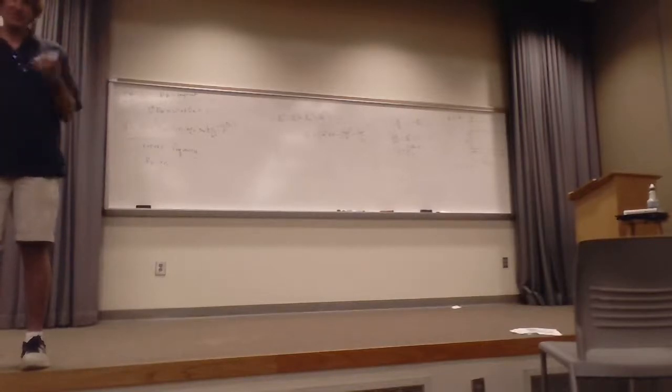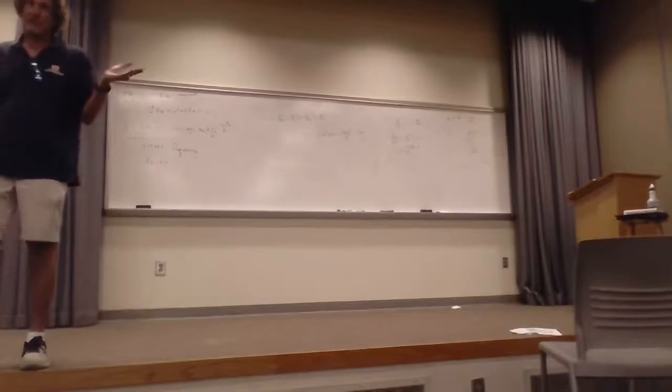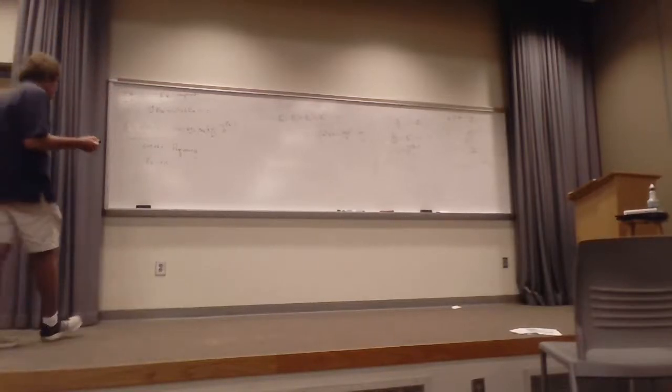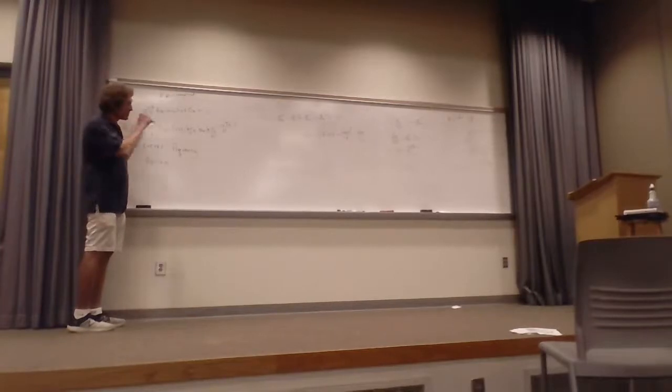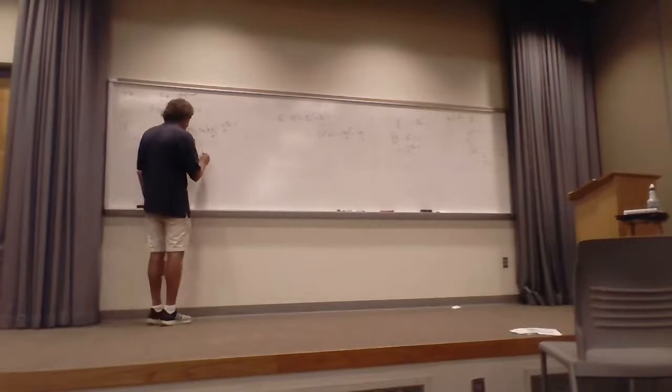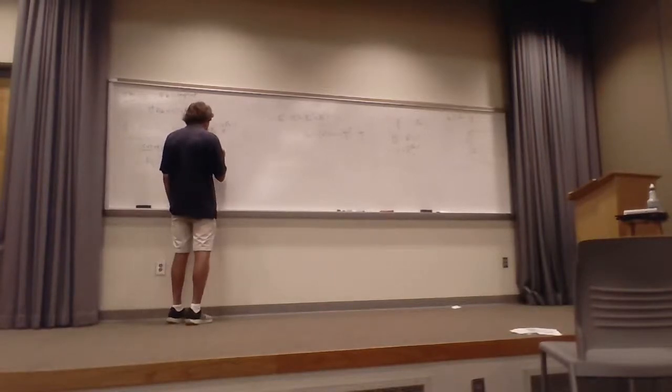It's not moving this way, all right? That's what it means. There's no z movement. It's only bouncing between, it's a capacitor effect, basically. A weird looking one, but that's it. All right, so when beta z equals 0, we call this the cutoff frequency. So this occurs at the omega cutoff frequency or at 2 pi f cutoff frequency.